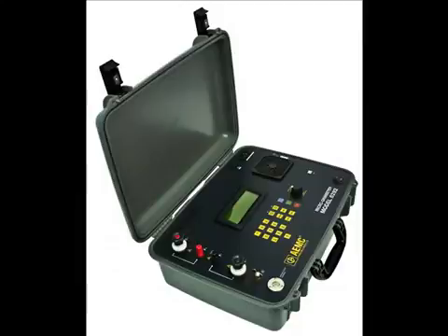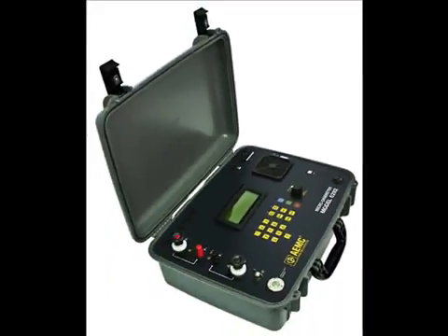The Model 6292 communicates with the PC through a USB connection. Therefore, the first step is to connect the instrument to the PC by inserting one end of the supplied USB cable into the instrument front panel. The other end of the cable will go into an available USB slot on your PC. Once the device drivers successfully load, you'll be ready to connect through DataView.